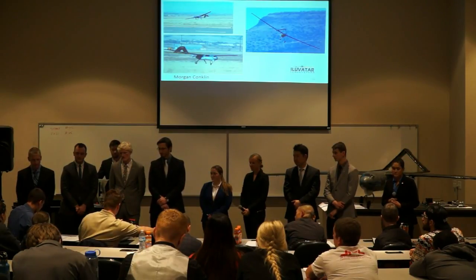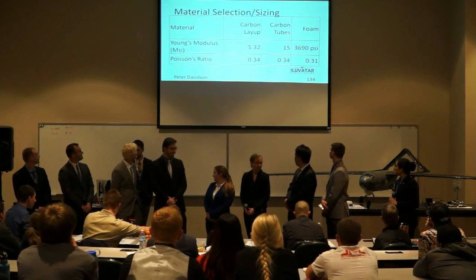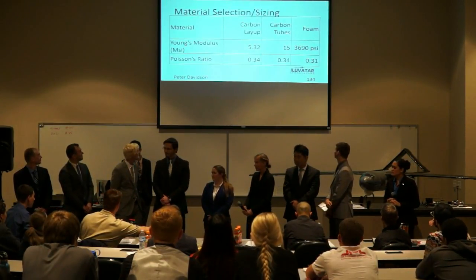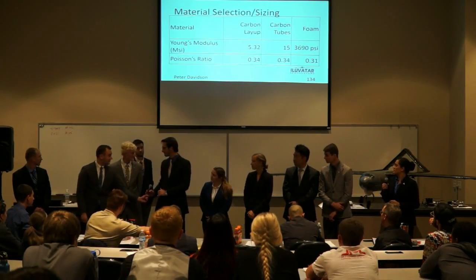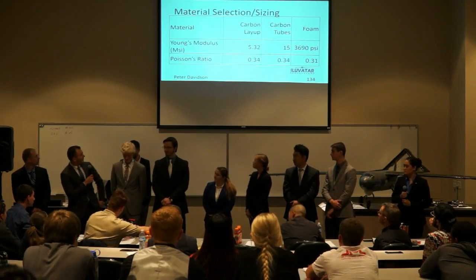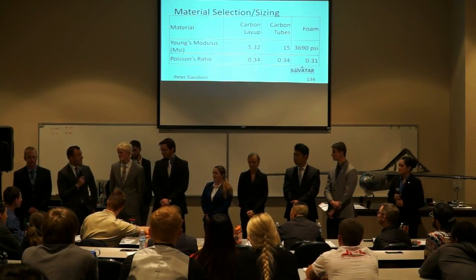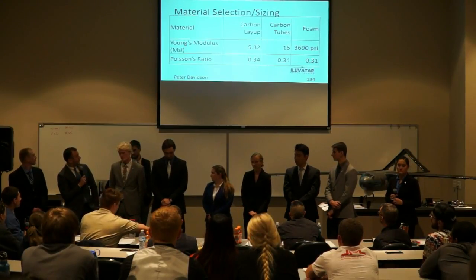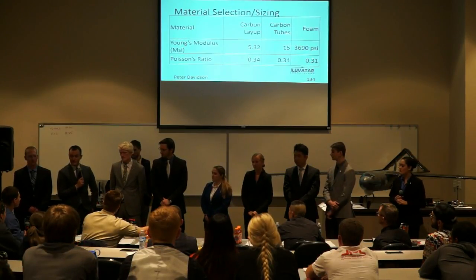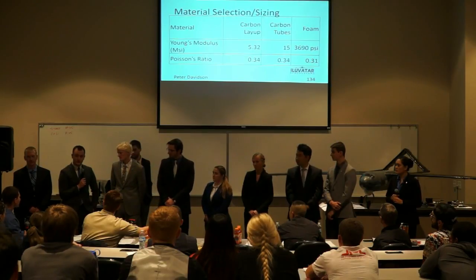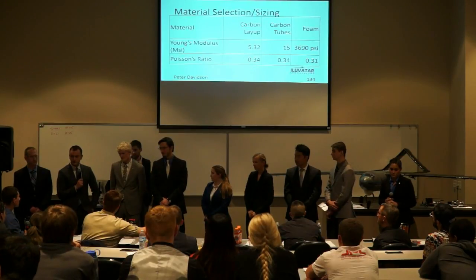I had another question. Slide 134. So I found the foam Young's modulus, but where did the carbon layup and carbon tube values come from? Andy, did you want to take this? So the carbon layup Young's modulus actually came from testing, with 0.34. And the foam was from testing as well. But for the tubes, the manufacturer actually didn't supply Young's modulus. So basically, we assumed it was made out of carbon. We made the assumption that it would be approximately the same as the 0.34. So that's where that assumption came from.